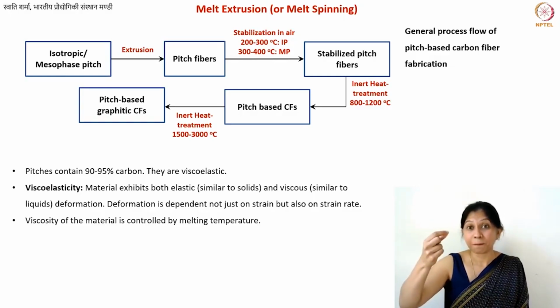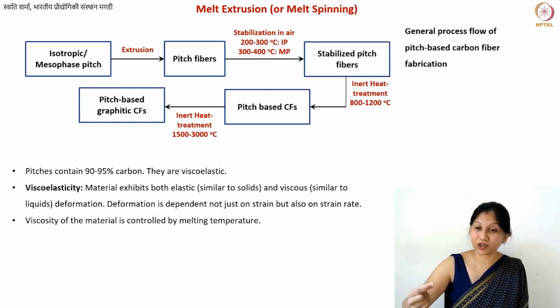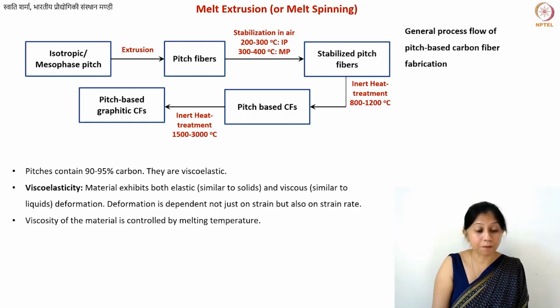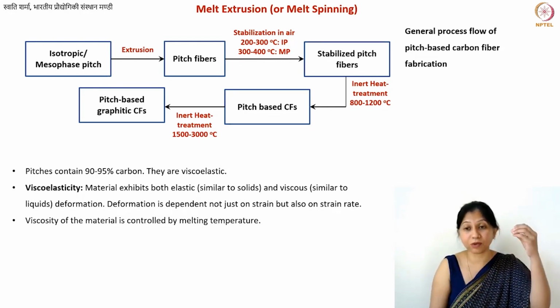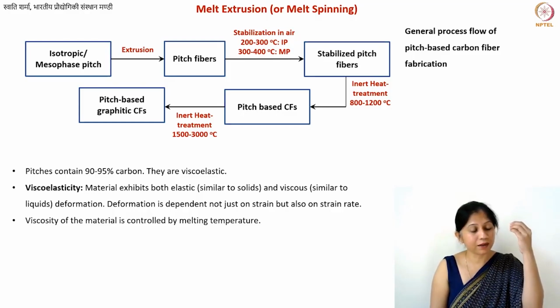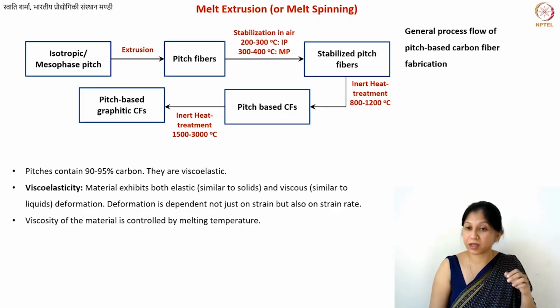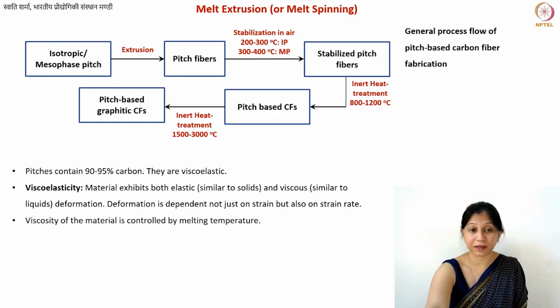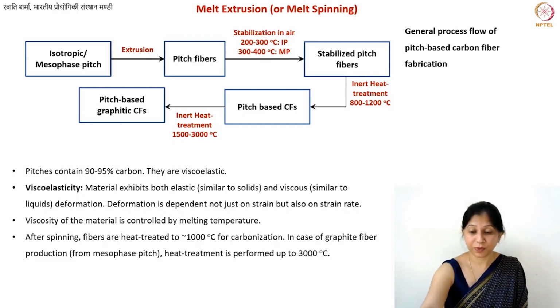Thin fibers, how long can they be? How long is their aspect ratio? What is the possibility there that we need to optimize? And then if you have these very viscous fluids like honey, then you can pull fibers, but what is the minimum diameter you can get from these fibers? These are the things that are optimized for the various materials that are being spun. Okay, so in the case of pitch, we control it by controlling the chamber temperature.